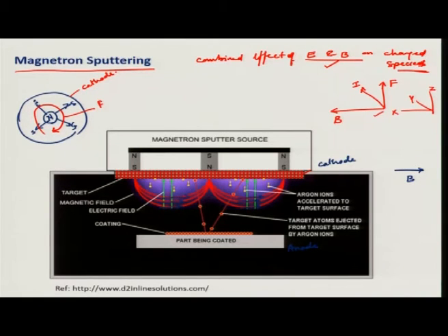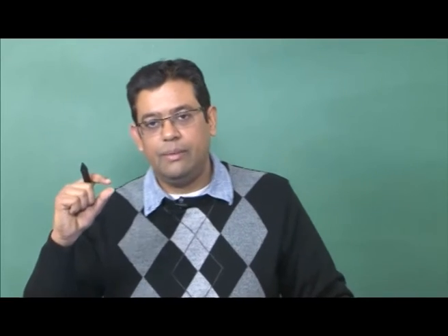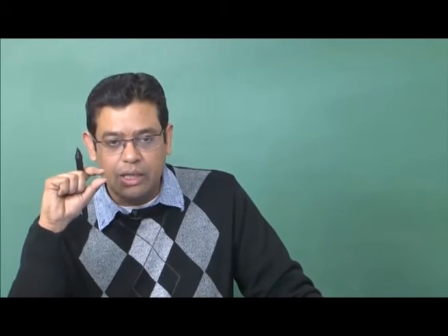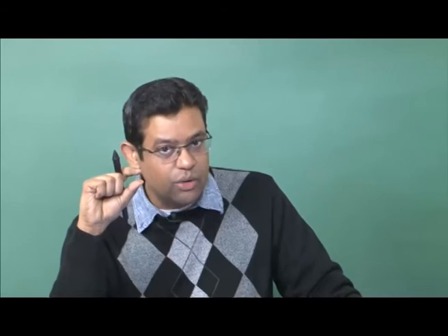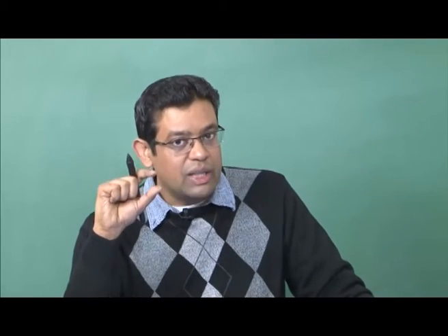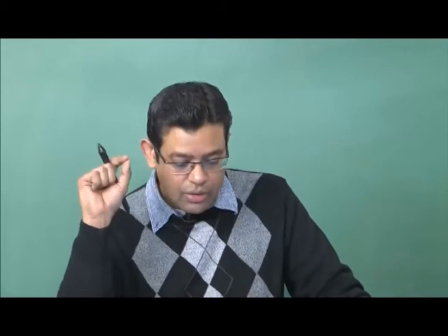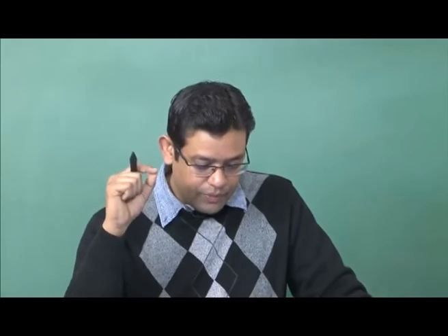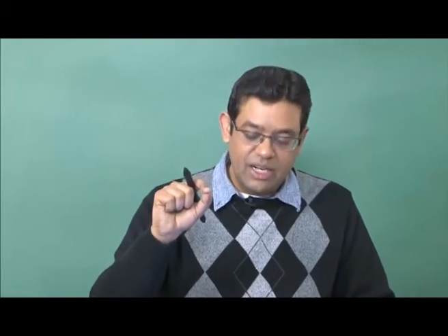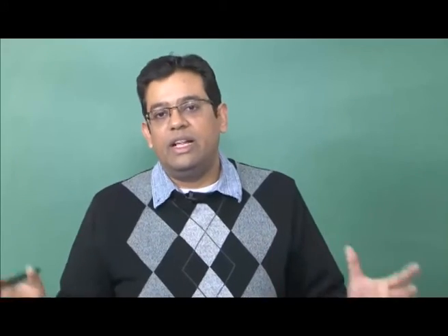Since the electrons are very close to the cathode surface, most of the ionization is happening close to the surface of the cathode, and remember that most of the potential is at the cathode dark space, which is very close to the cathode. So, all the potential is just there. So, ions are accelerated in that potential without being lost anywhere else.